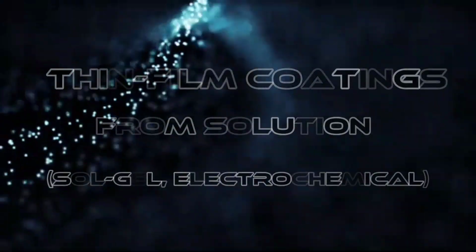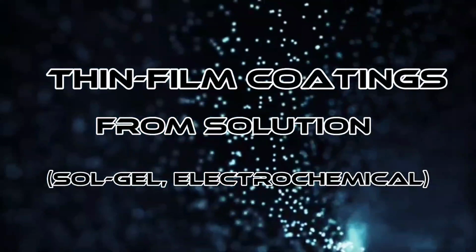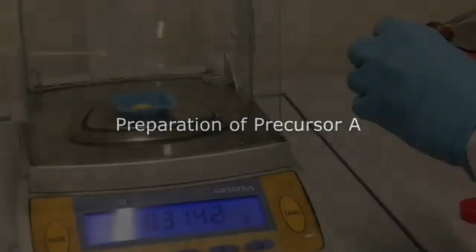Thin film coatings from solution involve processes like sol gel and electrochemical techniques. Sol gel converts a liquid precursor into a solid gel, which is then deposited as a thin film. These coatings exhibit versatility, adhering well to various substrates such as glass, ceramics, and metals. Here is an example process of a sol gel method.